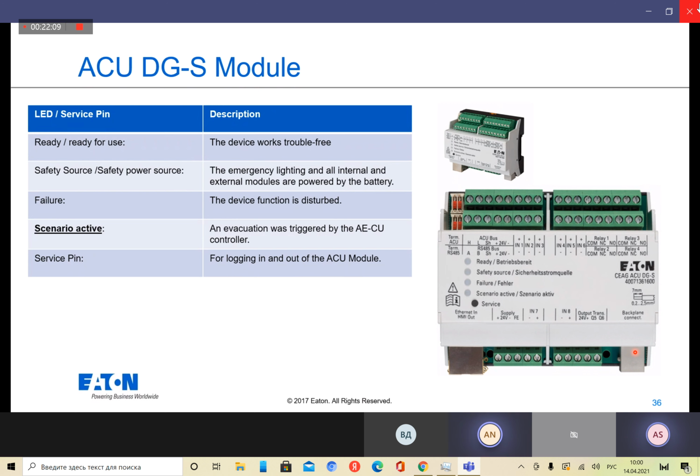I have a question, sorry. Two questions. So input 7 and input 8, is it an analog input for some kind of sensors and so on? No, it's a digital input as well. It's just located here because they would like to have the relays on the top right. This is a standard digital input, used if you order an E30 cabinet and the temperature sensors are not connected analog, just the relay outputs in case of a failure. This is a digital input as well. You can program it as well to S3, S4 if you would like to do it.